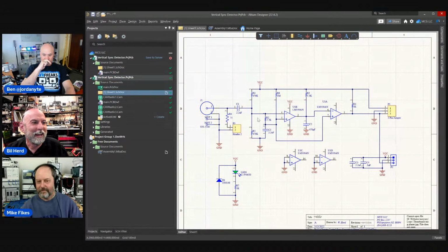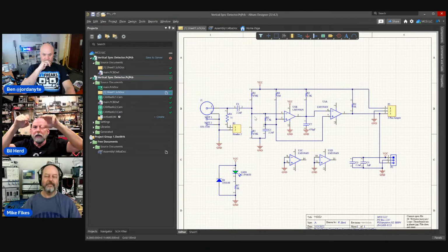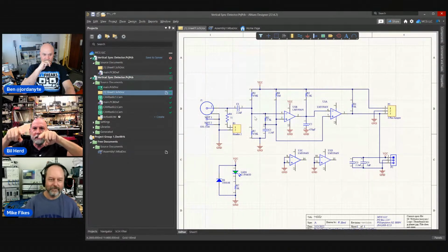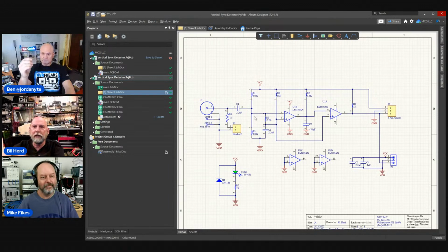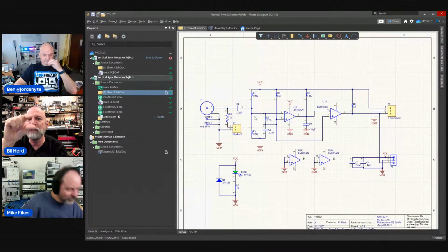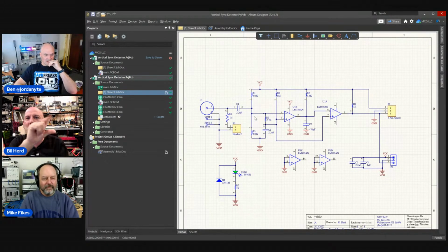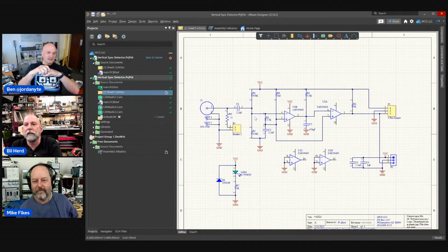learning tricks. What the depth finder did was, when it first does a pulse, it wants a high reference to compare to, but then as time goes on, the signal gets weaker and weaker. So this would track the baseline after each ultrasonic pulse. Decay, yeah. If you just did an absolute value, it would swamp it in the beginning and be too small at the end. So you need something that adapts. This is an adaptive baseline for a comparator.